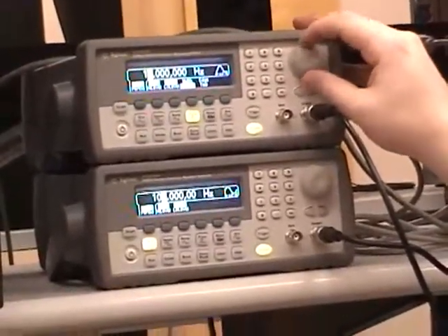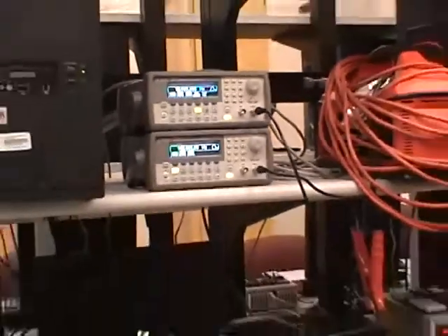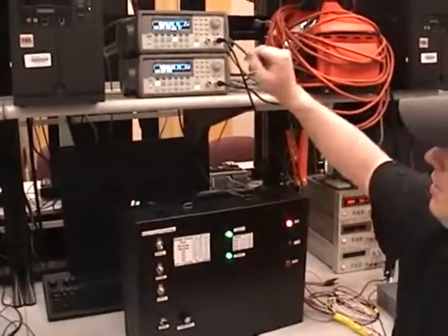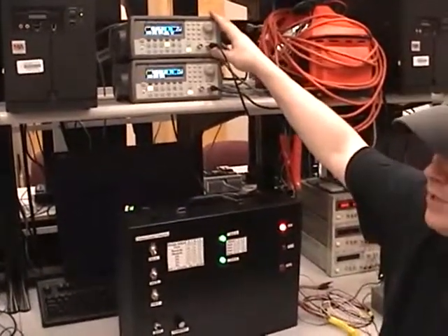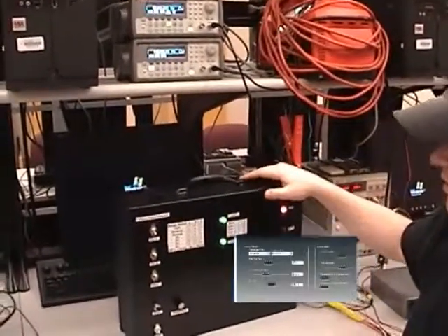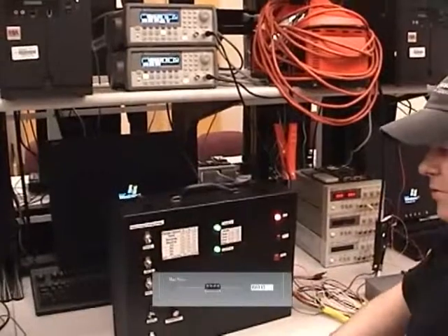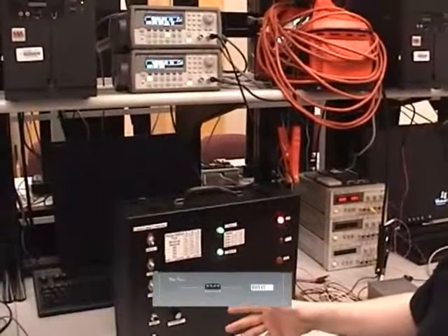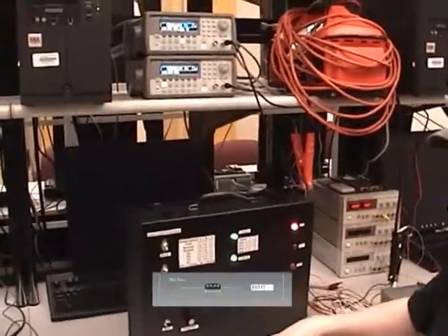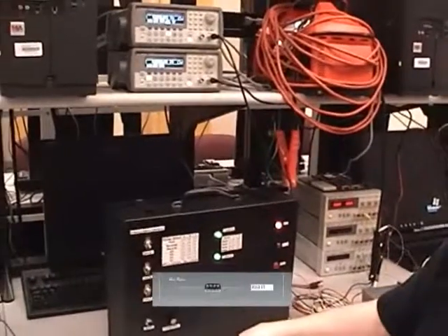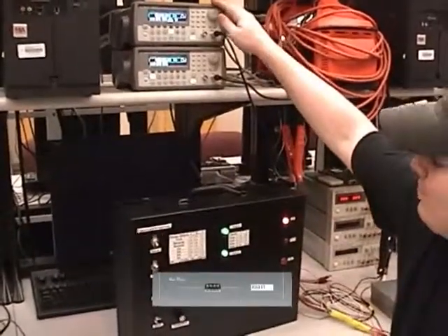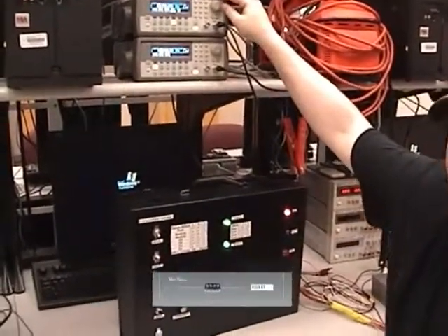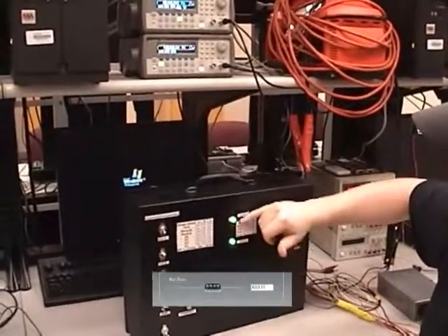And basically this is showing you exactly what the RPMs of the engine are. It's not being calculated from the VSS. It's straight off of the distributor. And the one thing that we're using this for is for a max rev limit. So if we set a max rev limit through the graphical user interface that we program this with, then you could set a value like, say, 4,500 or 5,000, and you know that your engine would be damaged at any RPMs higher than that. Well, then you can set that, and any time it's detected that your distributor signal is outputting higher than your max rev limit, it's going to cause these to upshift.